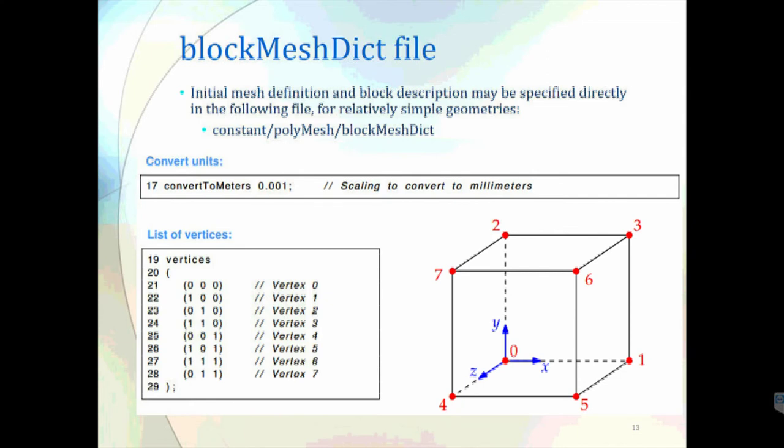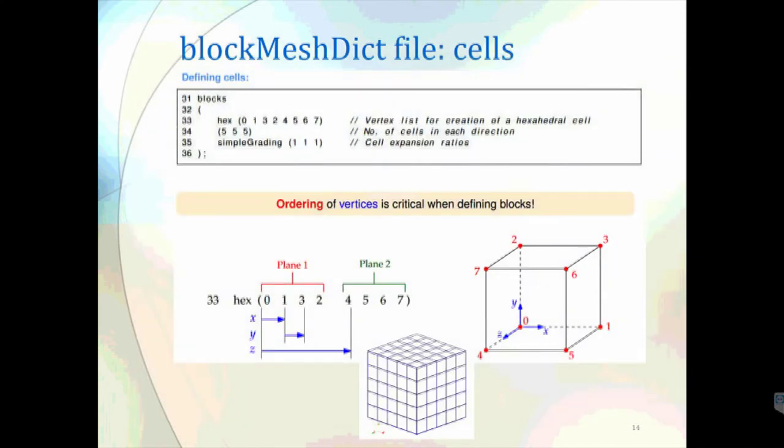But I have included several other examples as well in my presentation. So if you are confused about one example, you can go to another one. For example, this one, I was explaining to you earlier how to define blocks in OpenFOAM. This is the actual code screenshot which will be used to define the blocks in OpenFOAM. This file is the blockMeshDict file, and it is included in the system folder. I will show you the location in the folder later on.